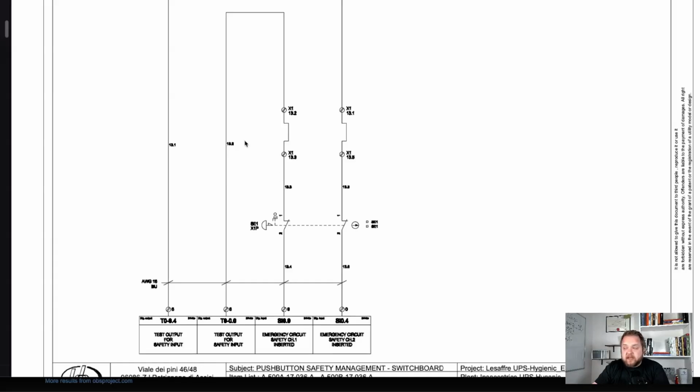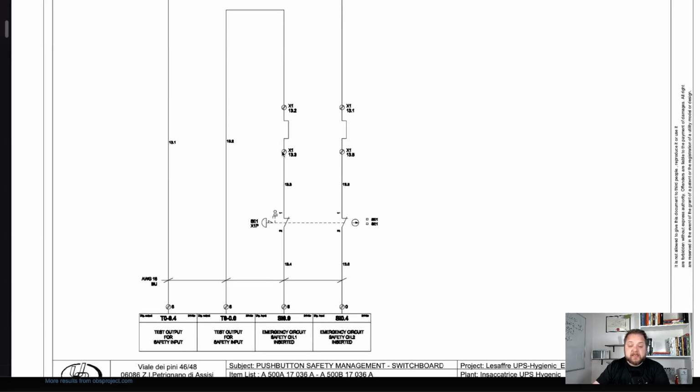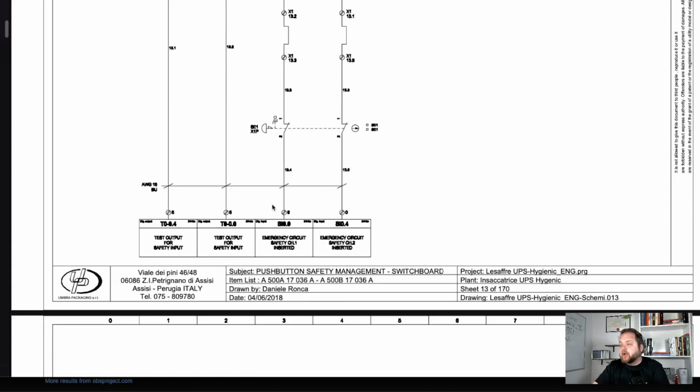So this is a very nice touch. I don't see all of the OEMs or machine builders include something like this. And as you have conversations with machines coming onto your floor, you definitely want to do a risk assessment and understand how your personnel will have to modify the equipment in order to meet the safety standards of your facility versus what the machine builder has built for you. And of course, they cannot account for all the scenarios on their side because they're building a system that is part of a line, but they don't know what the actual entire line might be.